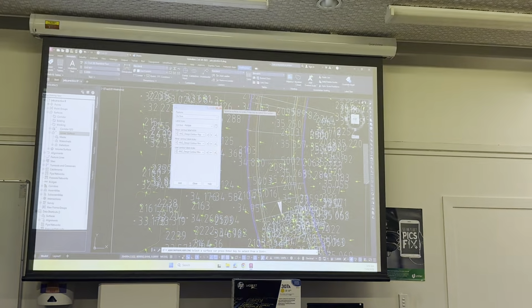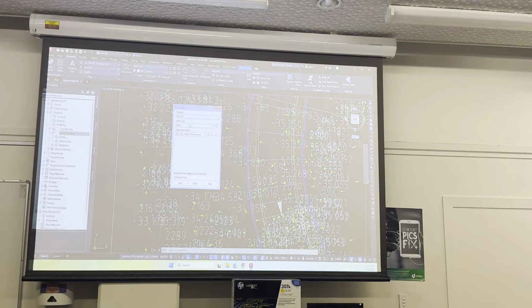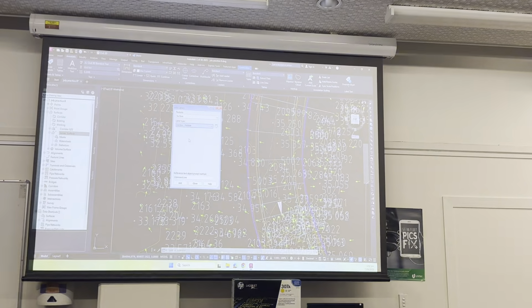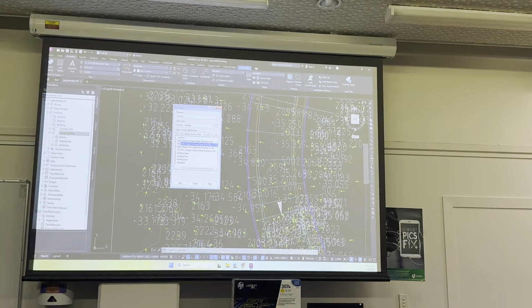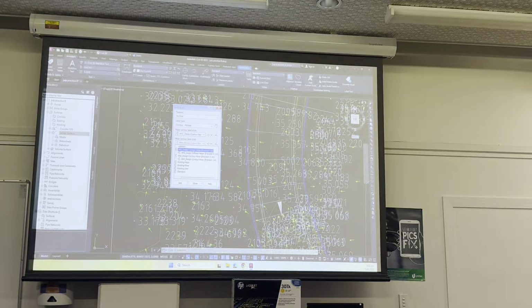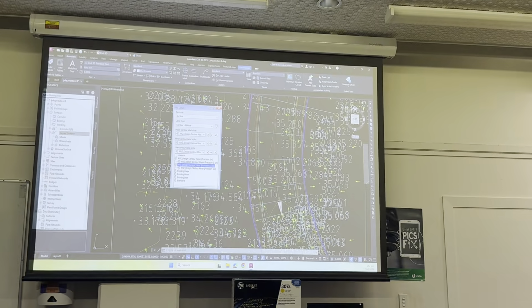So here, on the ribbon, we click annotate. Click on add labels, surface, add surface labels. You got up to this. So for this one, just use ANZ design contour major point one. For this one, use ANZ design contour minor point one. This one you can just leave as contour minor point one.